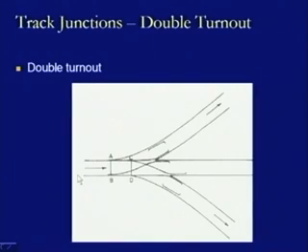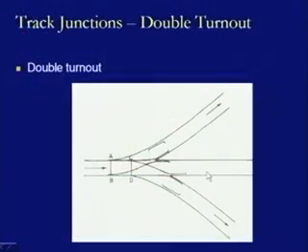Then we also look at another type of double turnout, where instead of a similar flexure we have the contrary flexure, and this is the main line. This is again shown here, and we observe that there is a left hand turnout which is coming from the initial previous point, and the later point, that is C D, is related to another turnout which is coming in the right hand direction.